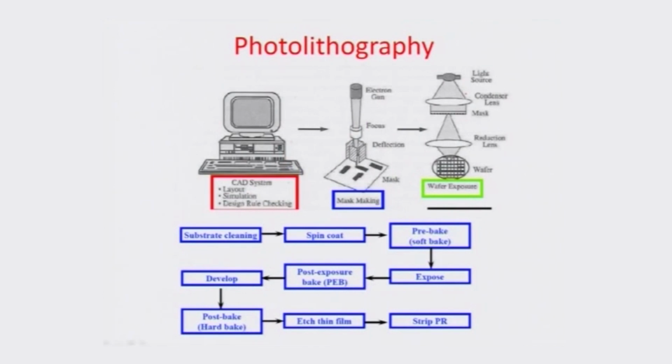If you look at photolithography in a step by step manner, it is illustrated here as an example. You have a mask surface, as you can see here, and this mask is made using AutoCAD files, and they are printed on transparency or hard masks. There is a light source at the top.